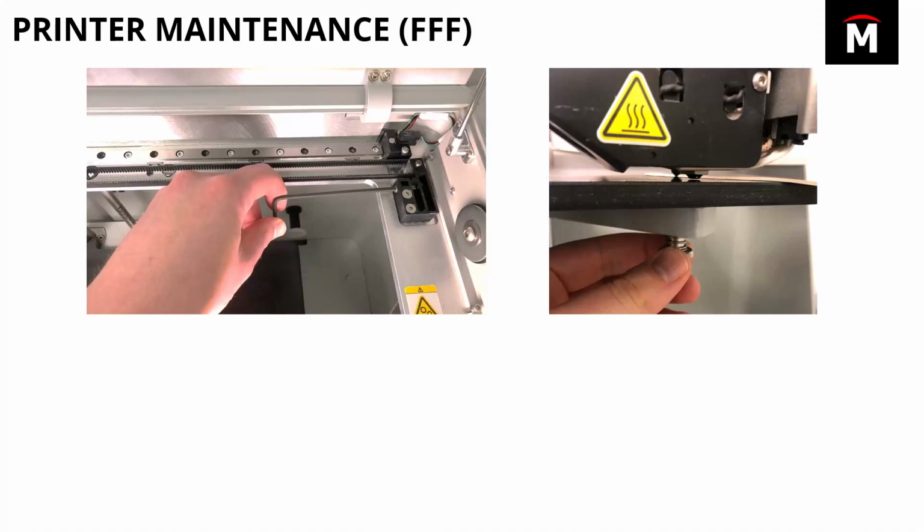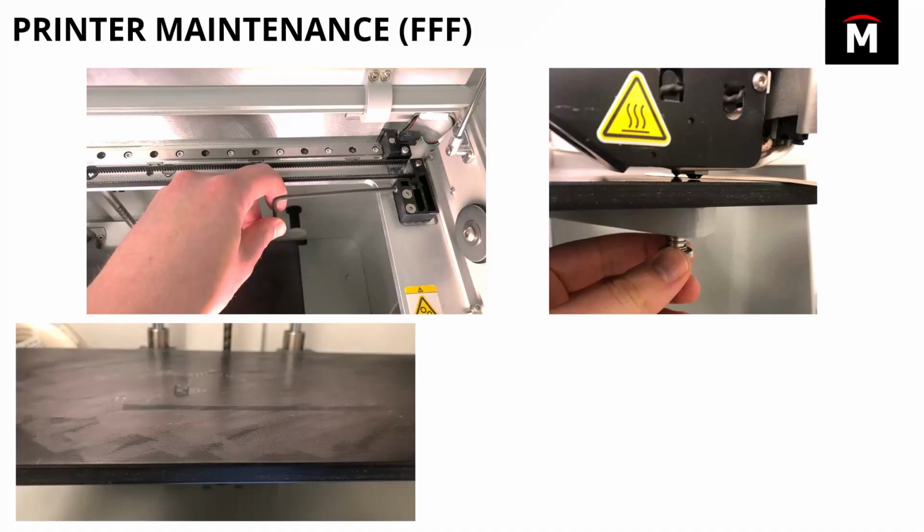You also want to consider how level your print bed is. So whether you have a shim-based system like the Markforged desktop, or a laser-based system like the industrial, or a mesh bed leveling system, you want to keep that print bed level. As you imagine, an off-kilter print bed is going to cause an off-kilter part. You also want to make sure your print bed's clean. So in this case, this print bed is not so clean. With Markforged printer, we use a glue stick to allow the parts to adhere to the bed. But as you build up layers and layers of glue over time, it can affect the ability for that first layer to go down, which can cause subsequent layers to be off and can affect the overall dimensions of your part.